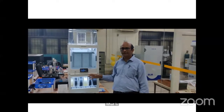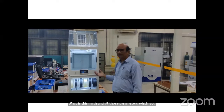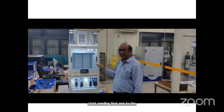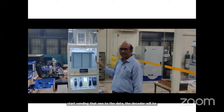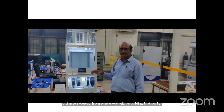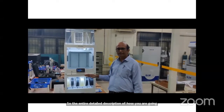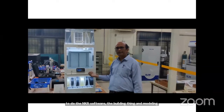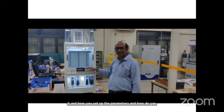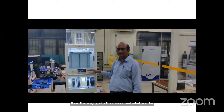And once you set those parameters, the G code will be generated. Based on that, the information will be sent to the Ultimaker S5 Pro, where you will be building the part. The entire detailed description of how you do this in Cura software, building and modeling the part, setting up the parameters, sending it to the machine, and the basic steps involved in the FDM process, from pre-processing to post-processing, will be